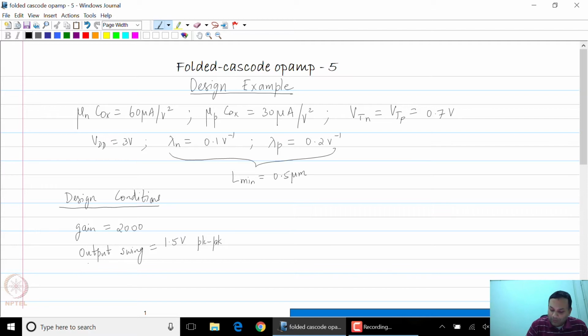and I'm going to give one more condition, which is the power dissipated. The power dissipation in the circuit, let us say, in the core circuit has to be 9 milliwatts. Now we want to see how to start off with these and come up with a design example with a particular design. And as we have done earlier, we are not going to set up a certain set of equations and try to solve for variables, because it's much easier to iterate than to set up the design conditions. So that is the system that we are going to follow.